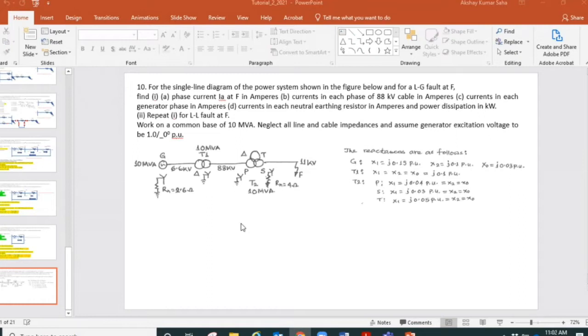Or is it because we can get a single phase circuit from it? Yes, that's the point. We'll get two different voltage levels, meaning we'll get line voltage and phase voltage. If I have 400, then we'll get 230 as well. So we need that kind of thing. Three-phase voltage, we'll get single-phase voltage as well. That is what we need in many applications. So when you need that, you must have star, because if you connect the three phases in delta, you will not get those two different voltages.